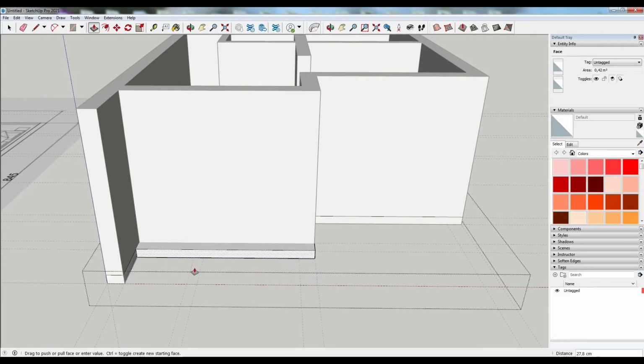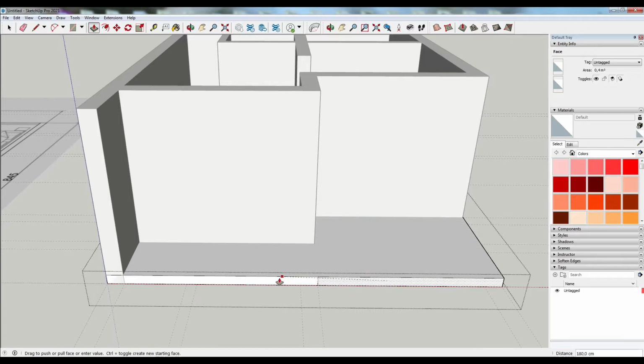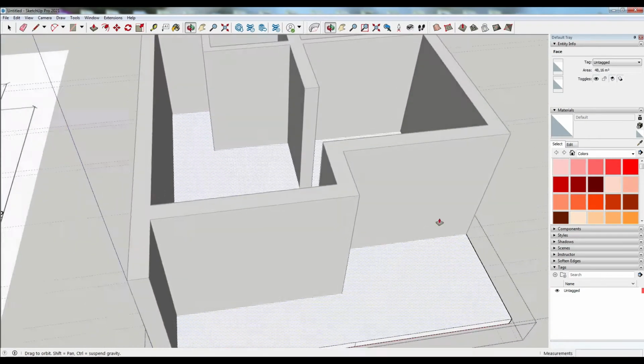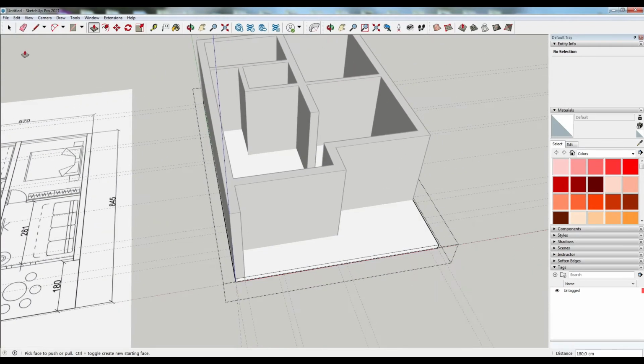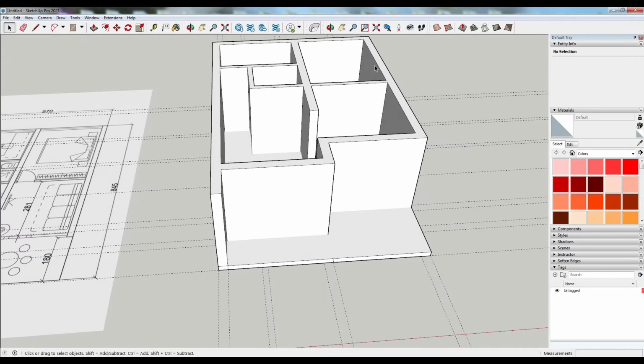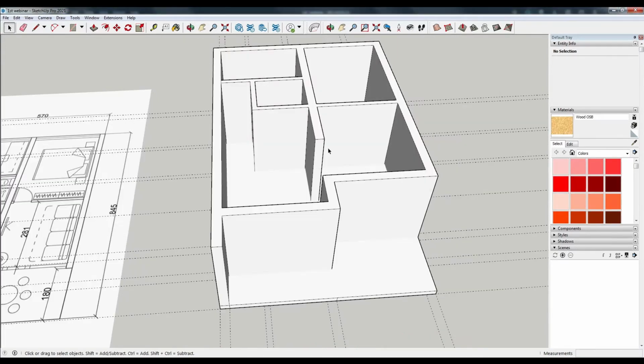We continue with making the terrace or the porchway by clicking on the side, showing direction, and with the push-pull tool we make it to the front line of the outline of the wall. As you may see, I could show a referential point or line in order to make it the same size. That's the way that I organize my objects and elements in different groups in order to make it easier to work with them.